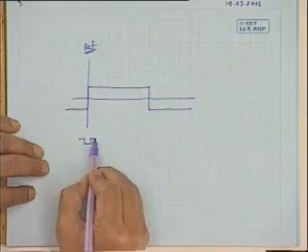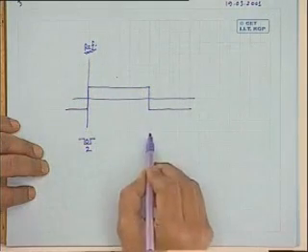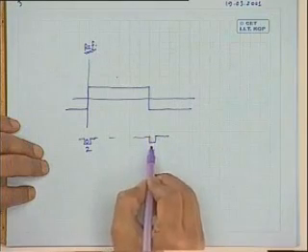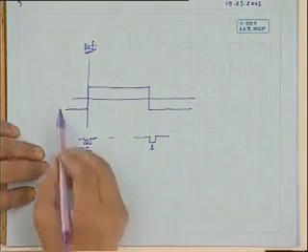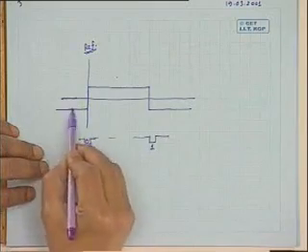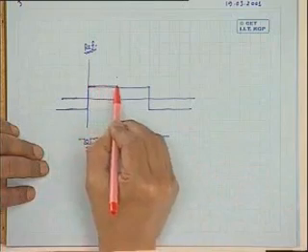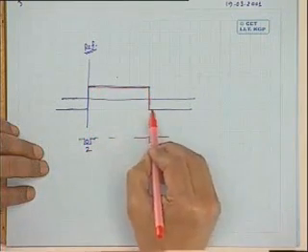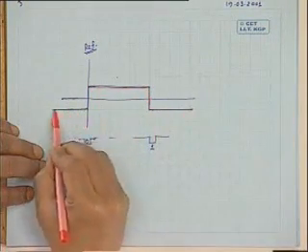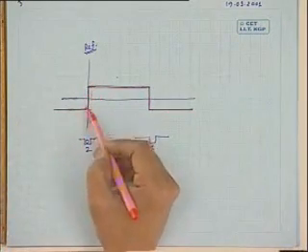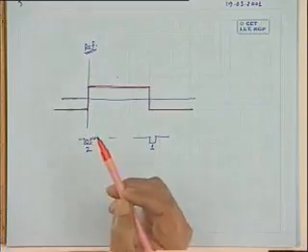That is slot number 2 here. This is slot number 1. So you will find the distribution of MMF along the air gap will be rectangular in nature. And in these slots there will be a jump. We do not know, it is undefined. But from plus to minus it will be like this.